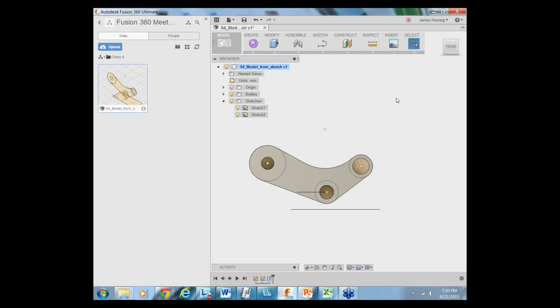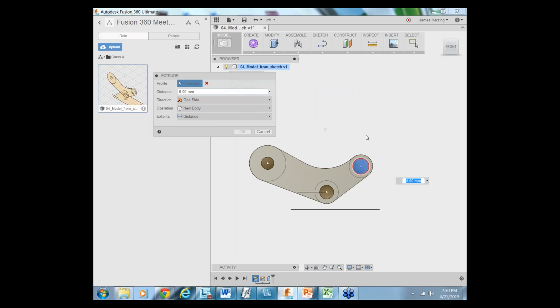We're going to start working a little more quickly in class now, and we're going to do that through the right-click menu. Okay, I know we're not actually going to, but in theory. So what we're going to do is select this circle that is filling that hole, and when you do so by left-clicking on it, it turns blue, and we're going to right-click, and you're going to see all of these great options available, and we're going to choose Extrude.